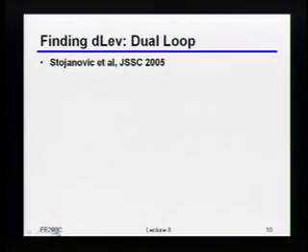practically what people tend to do is, instead of driving some variable gain loop, they just build a loop that figures out what the data level is in the first place. Okay? So I'll just quickly write what the update equation for that is. By the way, this was done by Vladimir Stojanovic, and the reference is in JSSC. Basically, let me just build a loop, and dlev is going to be the value of that reference.